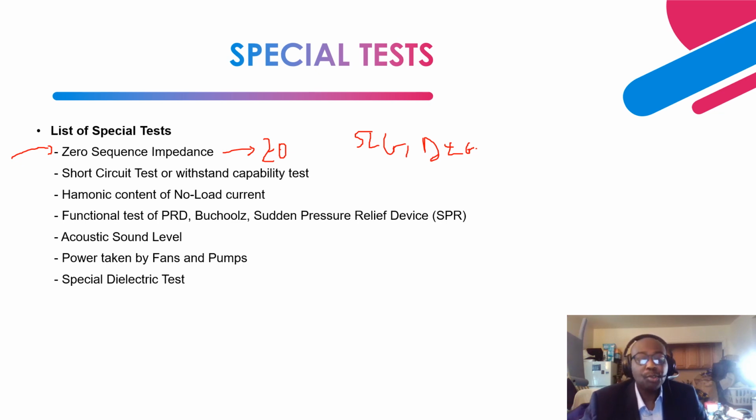As you know, to determine the sequence current, the path for single line to ground fault is shown by V divided by Z1 + Z2 + Z0. So this is the positive sequence impedance for the transformer, and that is equivalent to the nameplate impedance. And this is the negative sequence impedance, and this is the zero sequence impedance.